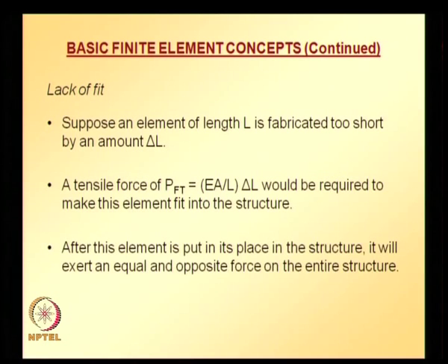After this element is put in place in the structure, that means a member that is too short is stretched by some means and placed in the structure, it will exert an equal and opposite force on the entire structure. Suppose instead the member is a little bit longer by a certain amount, then we need to apply some compressive force to force fit it into the given structure.